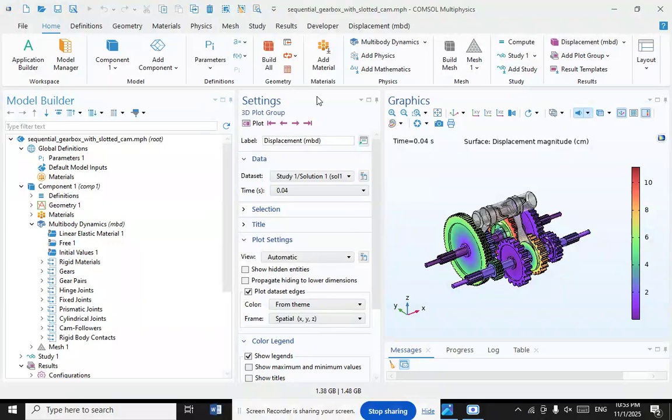The input shaft is connected to the engine and spins at engine speed whenever the clutch is engaged. The counter shaft has gears of various sizes which are permanently meshed with the corresponding gear on the input shaft. The gears on the output shaft are also permanently meshed with a corresponding gear on the counter shaft.